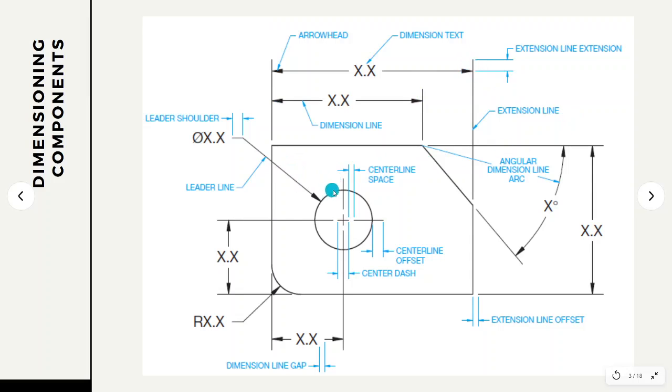Then of course, to make it more visually pleasing, we would be using leaders. Instead of placing a diameter like this, we could use a leader to call it out. We could use a leader, and a leader has a leader line and a leader shoulder.